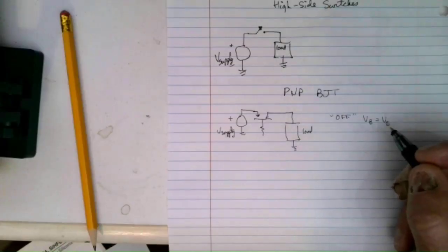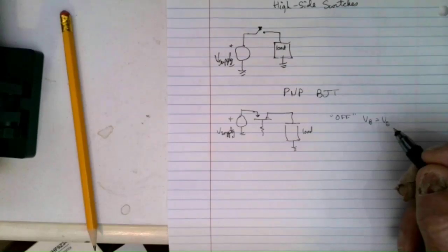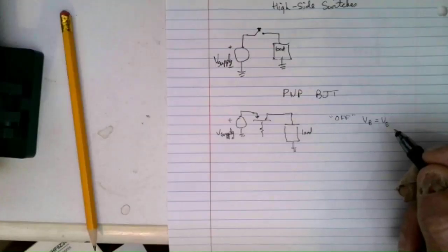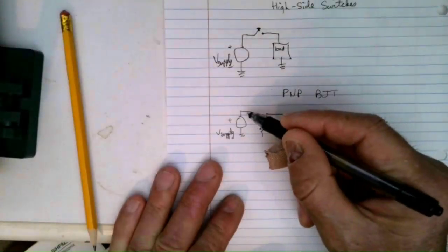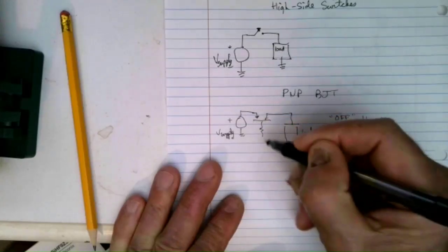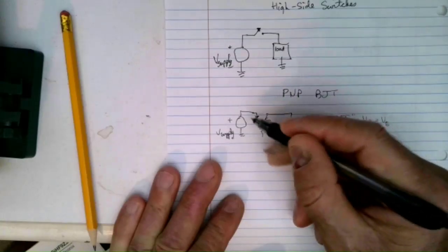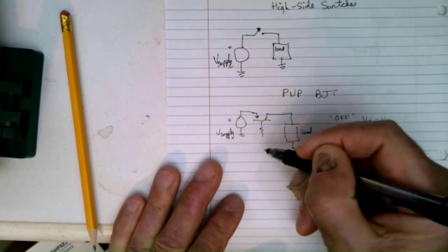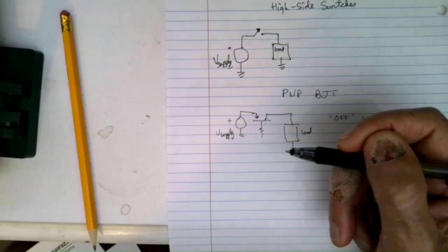But just as a quick guide, what would you like to see? So you don't have to think about it: if you let the base emitter voltage be 0, the part will be off for sure. And very often, this could be accomplished with a resistor here that pulls the base up to be equal to the emitter when you let go of this here. So you might put an NPN transistor down here, which turns this PNP on, and then when you turn that NPN off, a resistor here pulls the base up to the emitter and then shuts the device off.